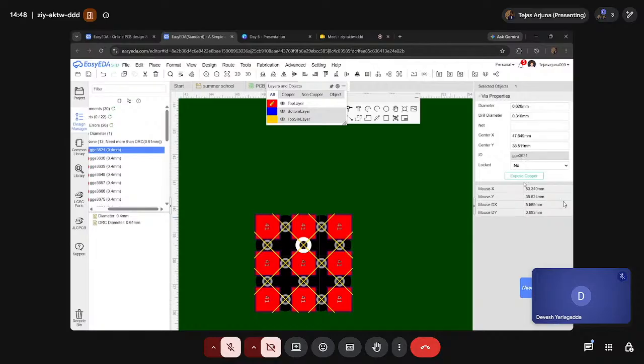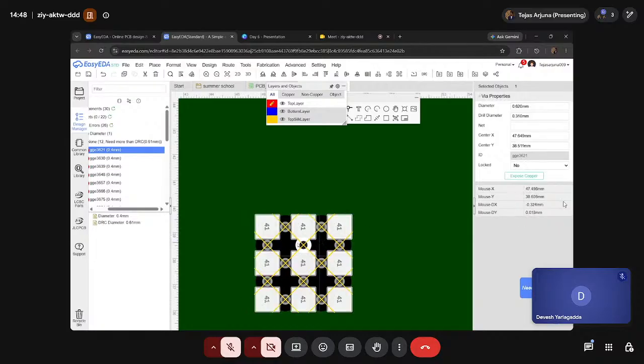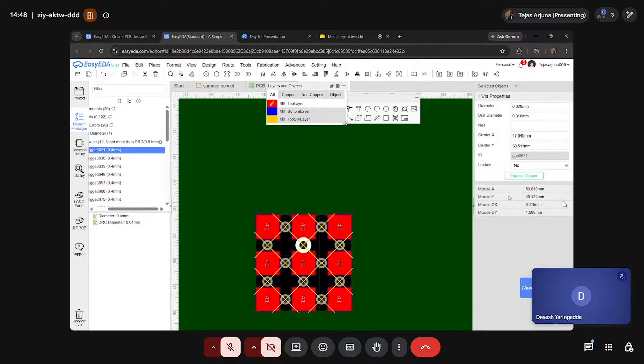If you don't want this wire to get interference externally, or want to keep the copper layer protected and avoid unnecessary metallic contact, we can leave this untouched. So do it for other wires as well, 0.62 and 0.31. If you do so, the design rule is matched, you are safe and the PCB is good to go.